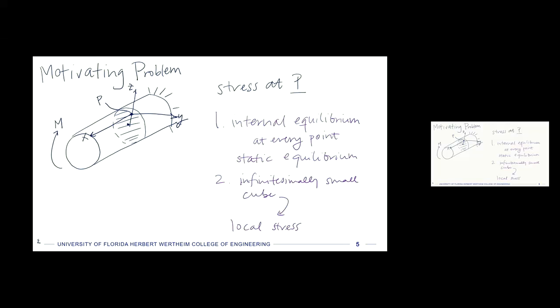Like, oh no, let's just use a rotating shaft until it fails and then figure out where that was. No, it's going to fail at a specific location, right? And so if we can define that location by the local stress, then we can pinpoint where that thing is going to fail. Okay. So first we'll define the variables on this stress cube, right?